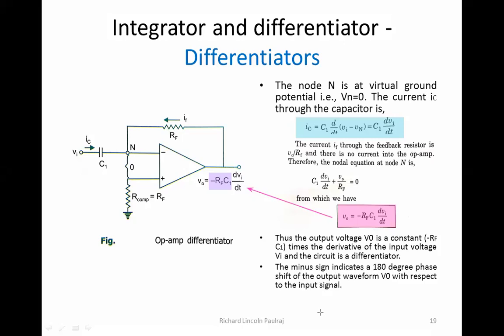Fine. So we are looking at a capacitor here, and we know that the current across the capacitor is C dV by dt. Now, here I have two voltages, V1 and Vi, so take those into consideration. Vi gets multiplied, so ultimately I am going to get C1 dVi by dt.